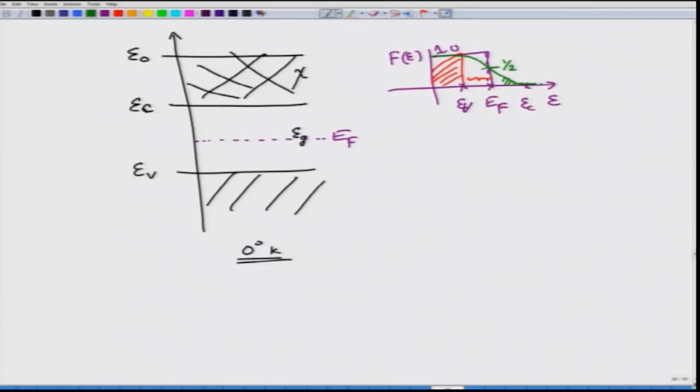As the temperature rises, some of the electrons can be found. So, when the temperature is greater than 0 degree Kelvin, some electrons can be found, leaving behind some holes, and this is exactly the reason why we had those plots of concentration looking something like this. You had this edge having larger concentration, and then as you move away about 2 kT or so, the probability would drop out.